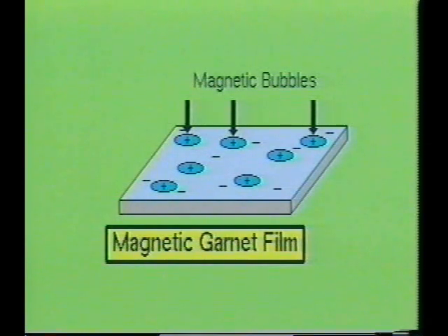These magnetic bubbles are about 5 micrometers in diameter and tend to drift in the thin layer of garnet. Like ordinary magnets, the magnetic bubbles will tend to repel one another. Since the bubbles repel one another, they maintain a certain distance between each bubble. This makes them suitable for use in a memory system. Now that you have a basic concept of what a magnetic bubble is, let's examine how these bubbles can be used to store data. We will begin by examining how the bubble memory device is fabricated.